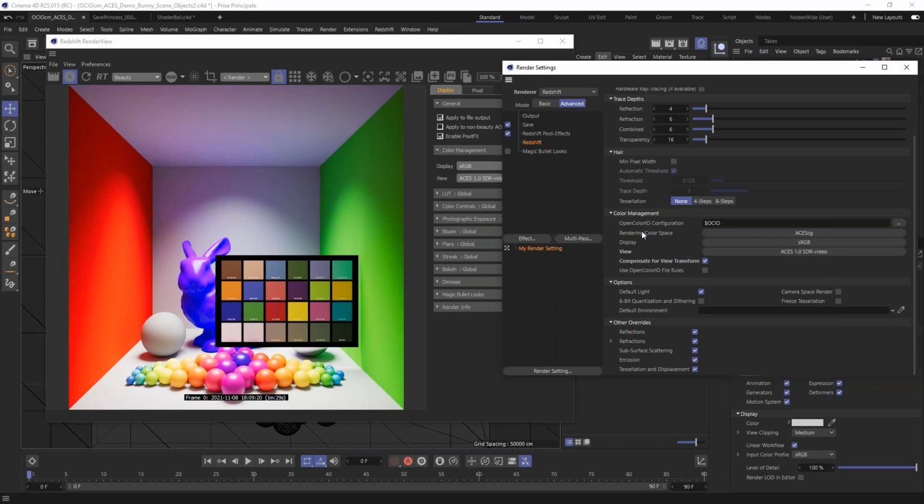To load the old behavior, the legacy behavior, you just need to change the rendering color space here to the working space, scene linear Rec 709 sRGB. And then here the view is going to be untonemapped. Okay, and now we can see this is much brighter and pure white actually, and we have some burnt areas. We can see here on the ground, some of the spheres are just too bright. We lost some colors on those here. You can see here all the orange and the yellow tend to be the same. Here the purple values are pretty bad also.